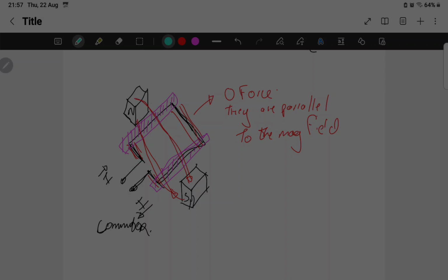I'm not sure if I can do it on here, but you can do it for yourself. Follow the magnetic field lines I showed you and the direction of the current. With Fleming's left hand rule, north to south, current over there, this side of the circuit has the force going down, and on the other side of the circuit the force is going up.